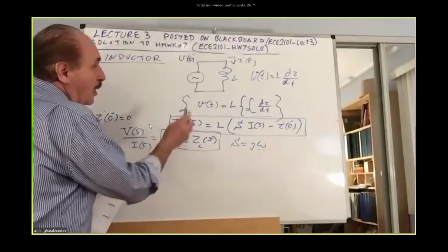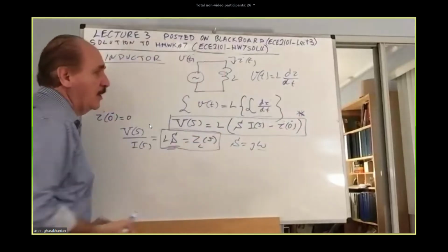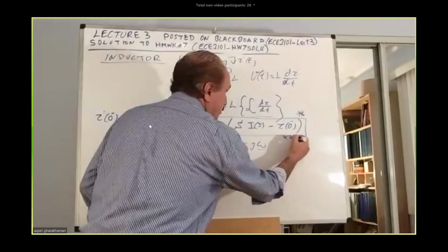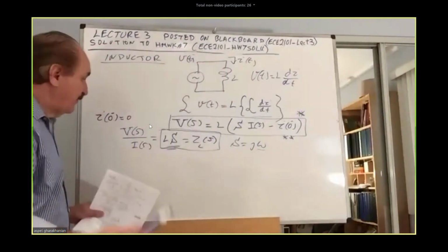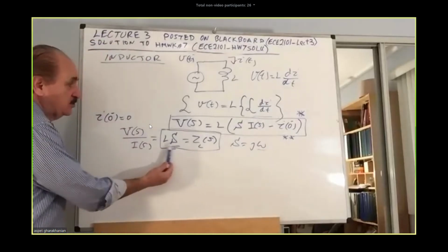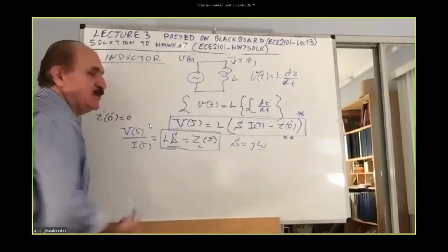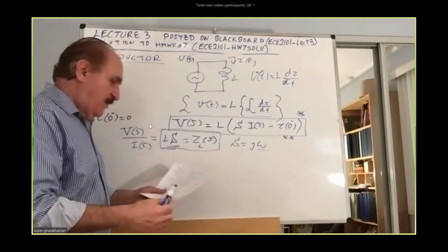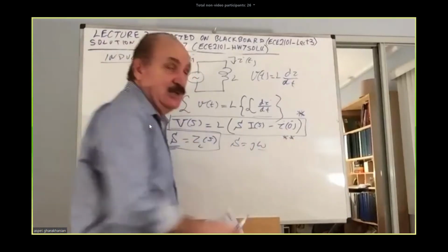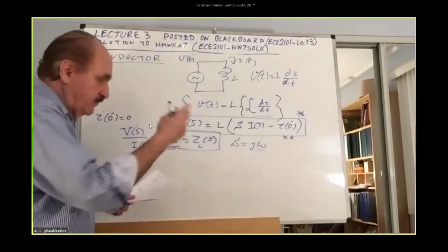So this is the general equation, the one that I put a star on, with the initial condition here. I put another double star on it with the initial condition. However, if you don't have an initial condition, it's 0, then it is even simpler. It's just Ls. The first product only counts, and you can come up with the impedance concept. However, I did examples with the initial values, just the way the book did it. I gave you some examples.